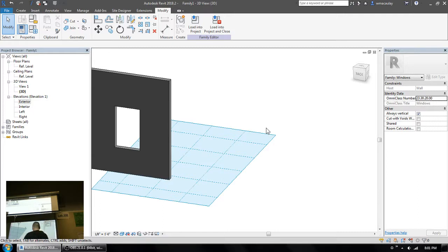Let's say that you are doing a door with a side light. And maybe that side light doesn't go all the way down to the floor. The side light is just partial. So in this case, you would already have reference planes for the sides of the door, the bottom of the door, and the top. So what we'd have to do for our side light is add an extra reference plane for that, and probably a reference plane for the bottom of the light at the side of the door. So that is how these reference planes work when we are dividing up a design that we have in mind for a new door or window.